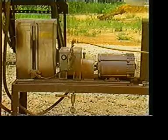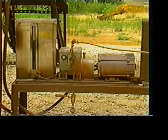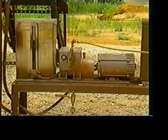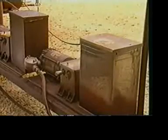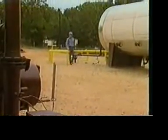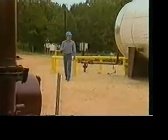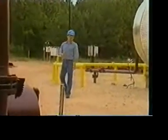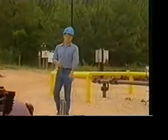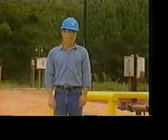The amount and type of chemical required directly affects how well the emulsion breaks and the time needed for settling. Warmer emulsions require less chemical. However, too much heat will cause the undesirable effects we mentioned previously. Electricity is also used to separate oil and water. Electricity is generally used in conjunction with heat and chemicals in an electrostatic treater, commonly called a chemoelectric unit. This form of treatment will be discussed in another module.